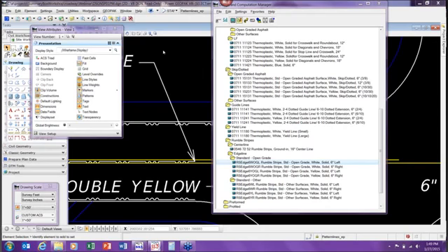The guidance is that we want to be using permanent tape on the bridges unless it's a bridge that meets the profiled thermoplastic criteria, and that's rural and over 50 miles an hour, but read up on those guidelines. Then you'd be using the profiled thermoplastic, but you wouldn't be using both materials on a bridge.